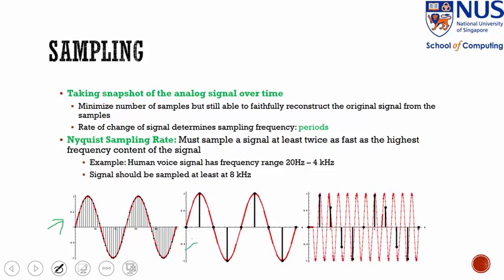Whereas in this waveform here, you can see that the samples are quite far apart. And if I were to try to connect the dots together, I will most likely be getting only a triangle wave, and not a sine wave. And in the third waveform, you can see that though I have more samples, it still is a bit misleading because from here, the first 2 points here make it go straight, whereas here I can get a curve. So it seems like half of it there is a nice sine wave section, but another half of it there is a straight line.